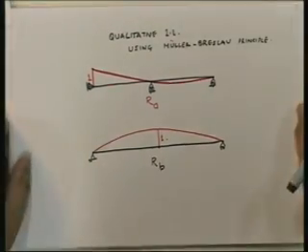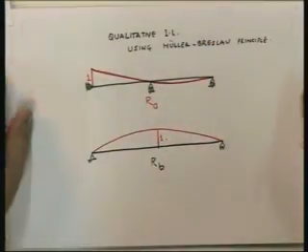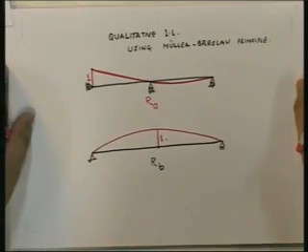this is the mirror. Understand that all we are doing is giving unit displacement. It's the same principle whether it is a statically determinate structure or a statically indeterminate structure. Because what the Müller-Breslau principle says is: release the restraint corresponding to the response that you are trying to find out, give it a unit displacement, and the deflected shape of the structure is going to represent the influence line.